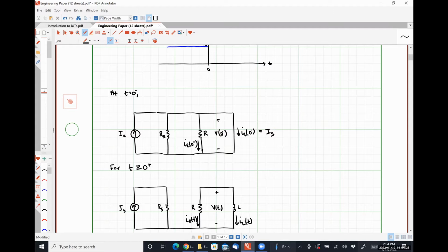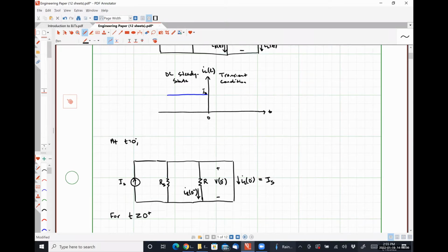What's going to happen as time progresses is that the inductor current will continue to flow, but it will now be forced to flow through that resistor R, which is going to slowly convert that stored electrical energy into heat. And as that energy transfer occurs, we should see the current flowing through the inductor slowly trickle to 0, because eventually all of the energy stored in the inductor will be transformed to heat by the resistance, okay? So at a very, very long time, let's call this t is equal to infinity,